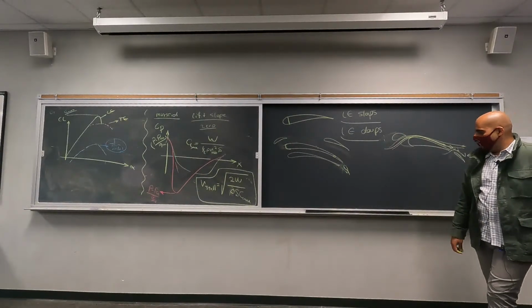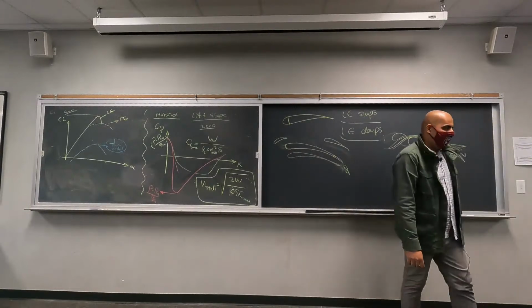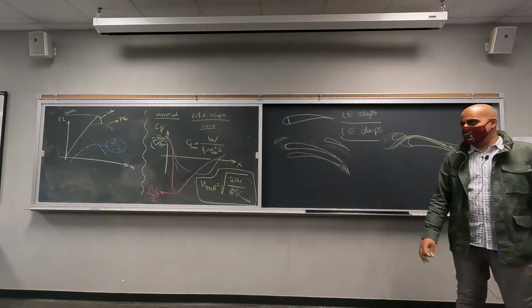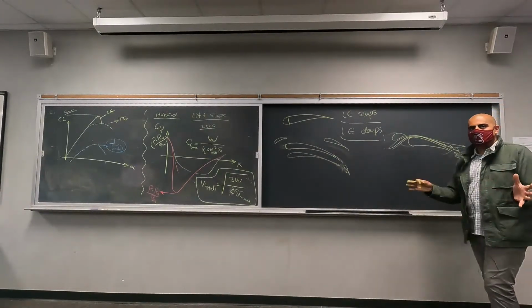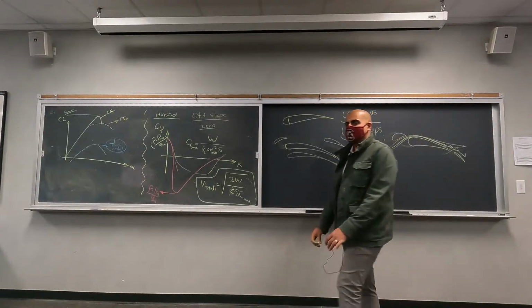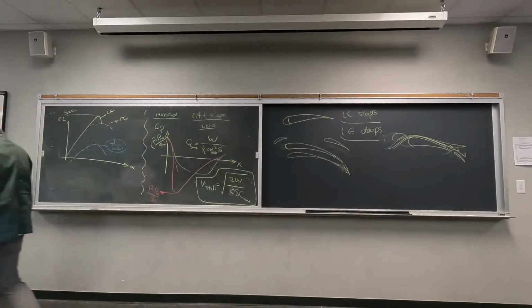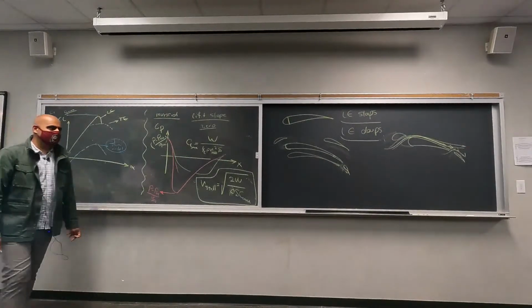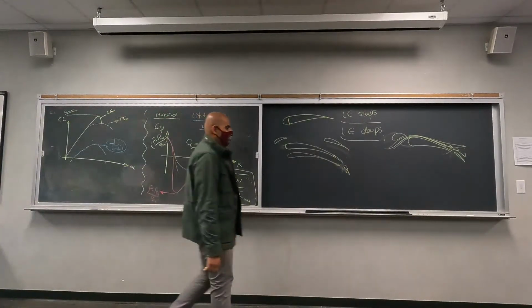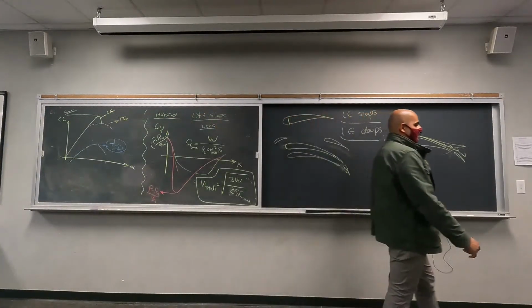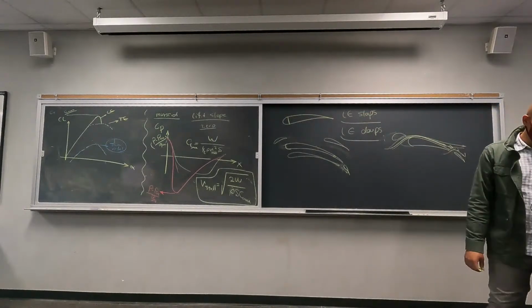Thanks for all of you chiming in. Okay, so we understand the high lift devices. We understand the two different mechanisms by which the high lift devices act: to increase the lift coefficient, or to delay the separation and increase the angle of attack at which your airfoil, your wing, can operate.